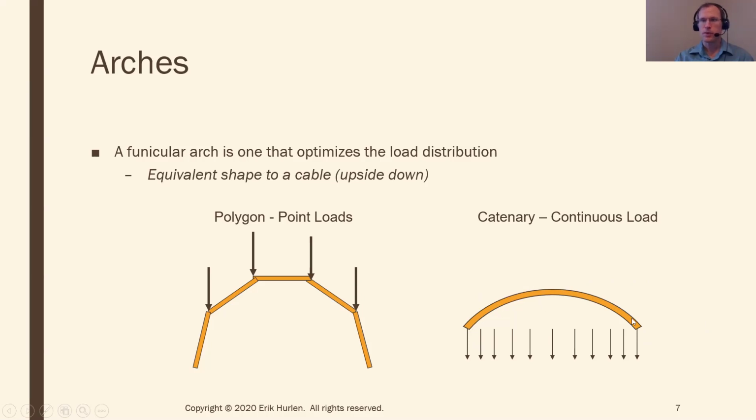And so that'd be the optimum shape if, again, it's supporting something that's like its own weight. If there's something that is supporting like a horizontal span, again, like a bridge deck, then you're looking at a more parabolic shape. So that's what you've probably seen a lot if you look at any sort of old stone bridge or something.